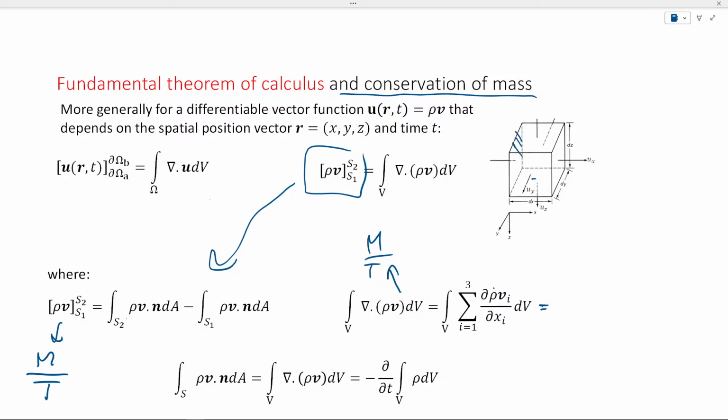So I have, let's say, this boundary, and I have this boundary. It's telling me the net mass flux across this boundary, as expressed by this relationship, is equal to, or not equal. It is equal to means what? Means it is the same as the net mass flux expressed as an integral inside this volume. That's basically what it means. So my net flux across the boundary, what's coming in and what's going across the boundary, is equal to what is changing across the boundary.